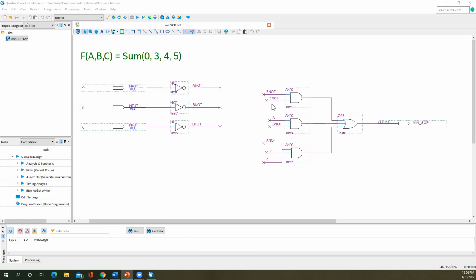And then if I use these names as inputs to the AND gate, rather than directly drawing the wires, we can actually name the wires and it will make the connection. So it makes our schematics, when we've got a lot of wiring, easier to read because we don't have wires laying over the top of each other. We don't have to worry about actually getting an incorrect junction when we're drawing a lot of wires. So I prefer to name my wires.